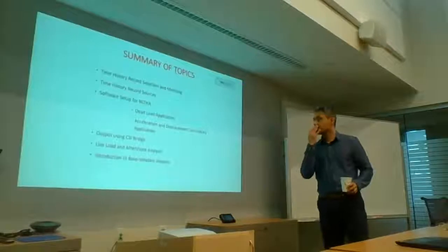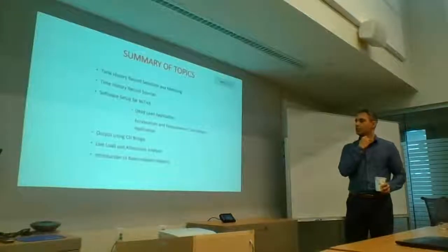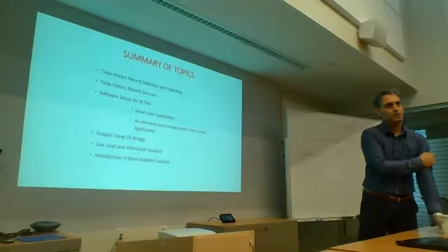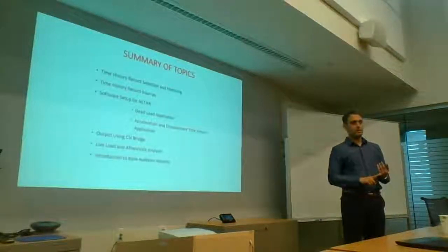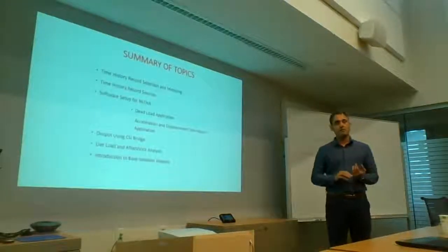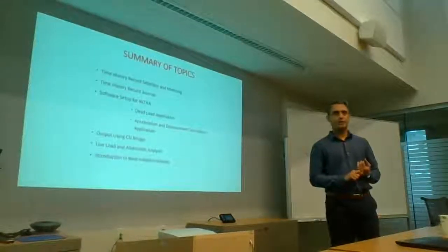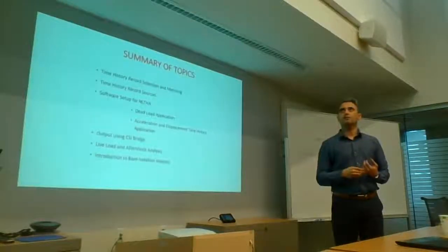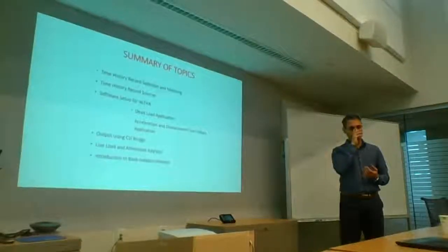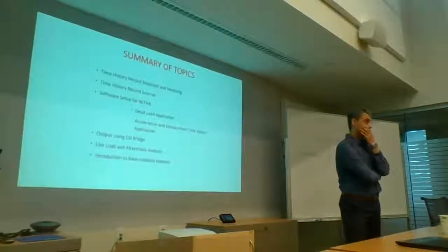Okay, so I think I touched on this a little bit. Time history record selection and matching we'll maybe have a chat about. Hopefully people are aware that on the coast we have 3 different seismic sources. We have the shallow crustal events that happen within the plate, like up high, 10-20 kilometers. The intraplate, or what we call the subcrustal events, and then we have the subduction event, which everybody talks about.